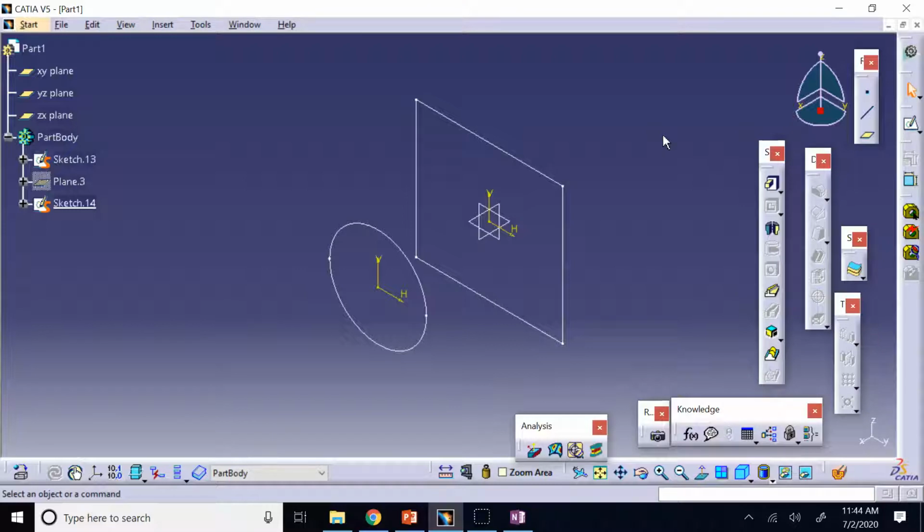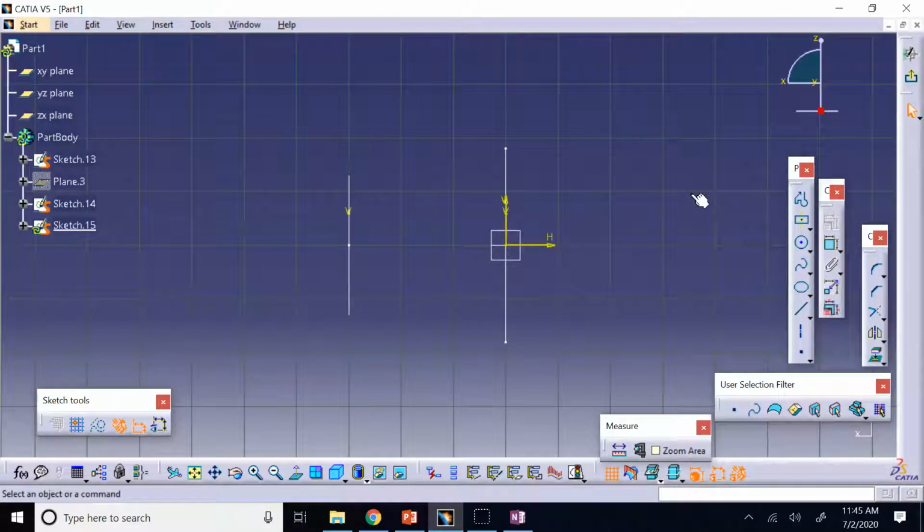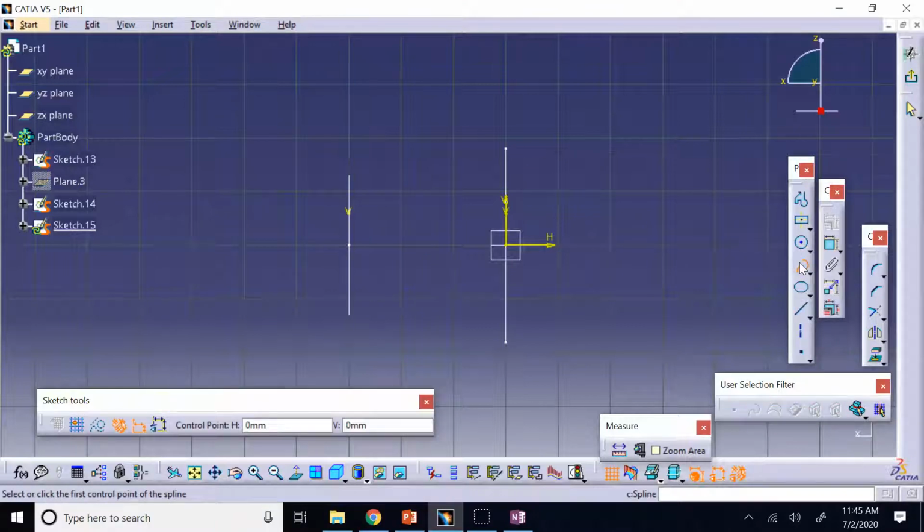The guides have to be created on the planes that are perpendicular to the original two planes of the profiles. So if I did these two guys on YZ and parallel to YZ, now for the guide I have to use either XY or XZ. So let's go with XZ. I have to see these guys from a lateral view. And then here I can create the sketch of the profile. Let's use a spline.